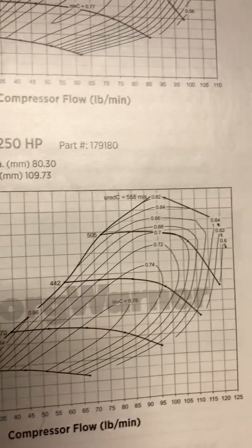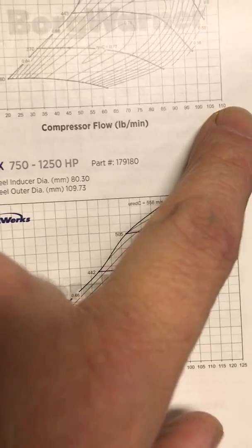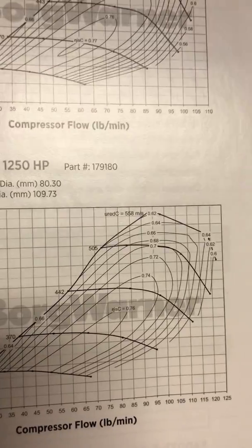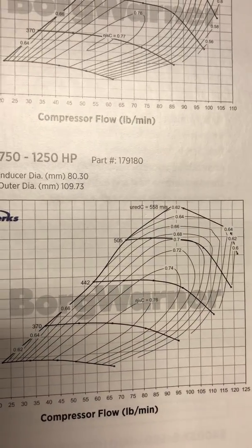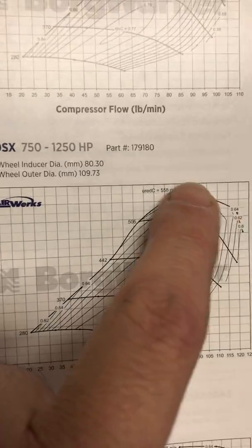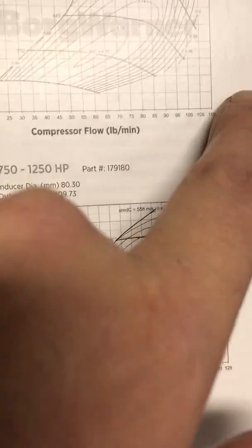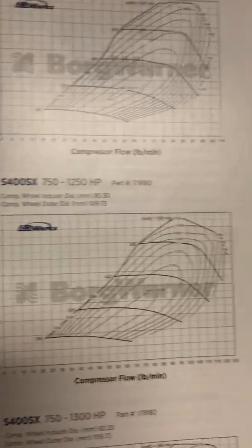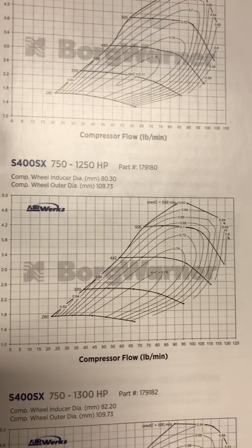So, the further you push the turbo off the map, the less efficient it becomes, which means you need even more pressure, and you're way beyond the limit of the speed of the compressor. So you're in danger territory. Reality is we often operate in danger territory. It's just what we do in performance.